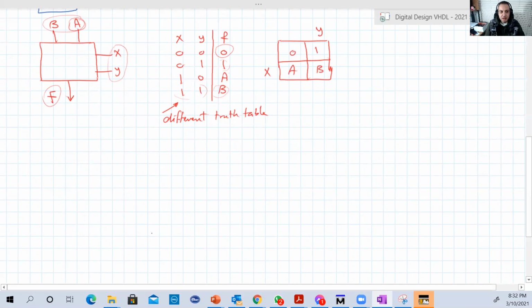Okay? In the Karnaugh map, when we combine a group, we combine a group that has similar stuff. Either the group should have all ones or all zeros. Okay? In some examples, we do examples in which we group the zeros, not the ones. For example, for F bar, F complement. So here we have 3 groups: this one, and this one.